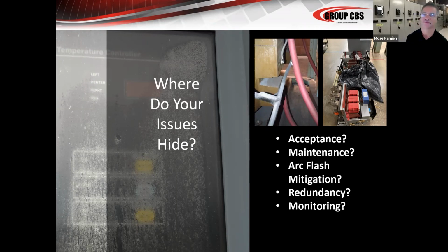Thanks for the presentation. Yeah, on that one, I get a call probably 2 or 3 times a year, asking how come the electrician that was wiring in the light switch and his screwdriver got, for whatever reason, he was working it hot, right? You shouldn't do that, but he was, and his screwdriver got between the hot lead and the metal case of the box. And instead of the 20 amp breaker tripping, or instead of the 400 amp breaker that feeds that tripping, it goes all the way back to the 4,000 amp main and shuts down the entire facility. And once again, that is almost always because of the ground fault setting not coordinating with the devices downstream.